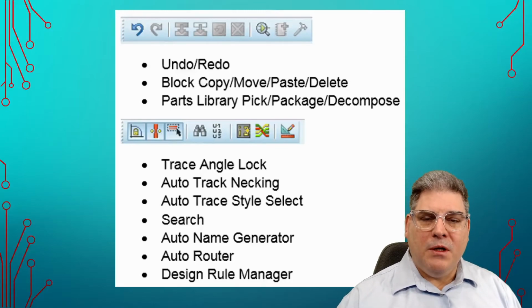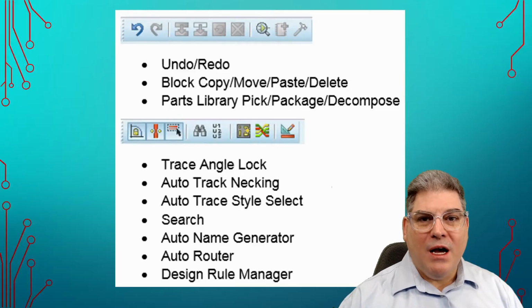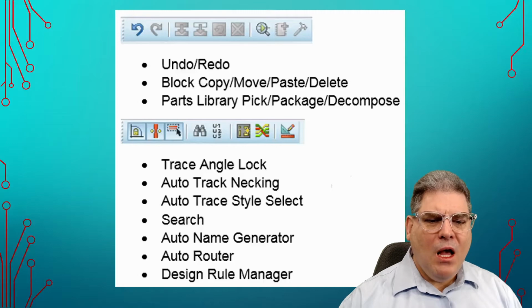So in case that I usually do, the top left corner is resistor 1 and resistor 2 is immediately below it, and so on and so forth. And it means that when we go to assemble our parts, it's easy to find a component. Okay.